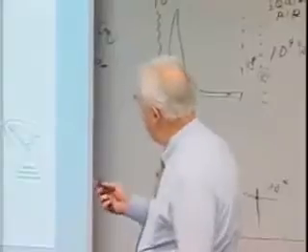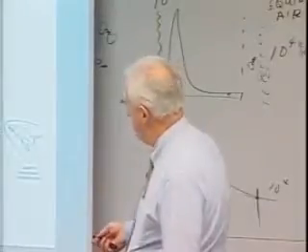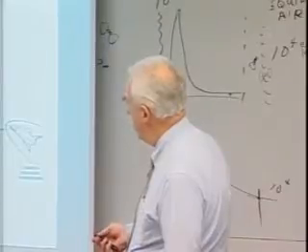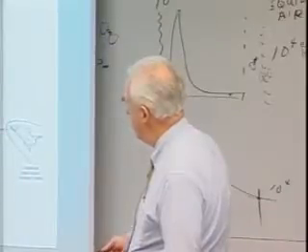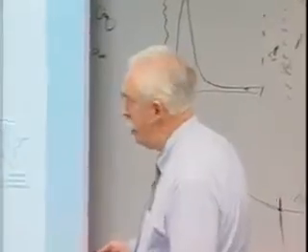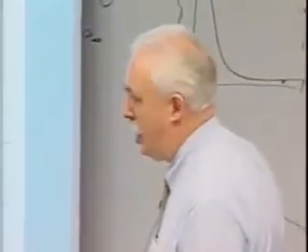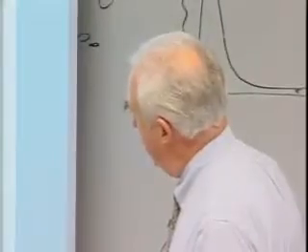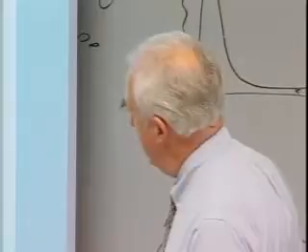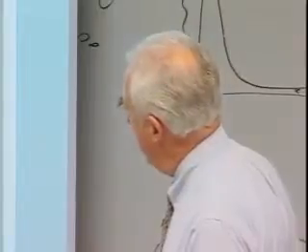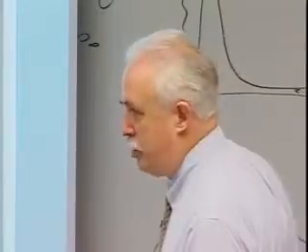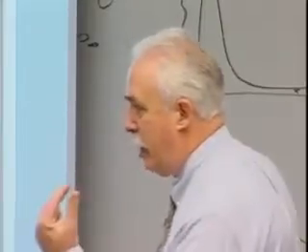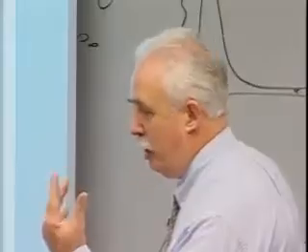Okay. This is just the concept, which again, as Aaron mentioned, is in the report. We had to go to arc jets and spectroscopic diagnostics and flow models of what's going on in the arc jet to understand the surface catalysis of tiles and carbon. We had to model the flow and model the chemistry, and come up with an efficiency. Then we go to flight with similar analysis and predict, and I'll show some predictions of this. This is a significant phenomenon at the high altitudes, low density for the Shuttle.